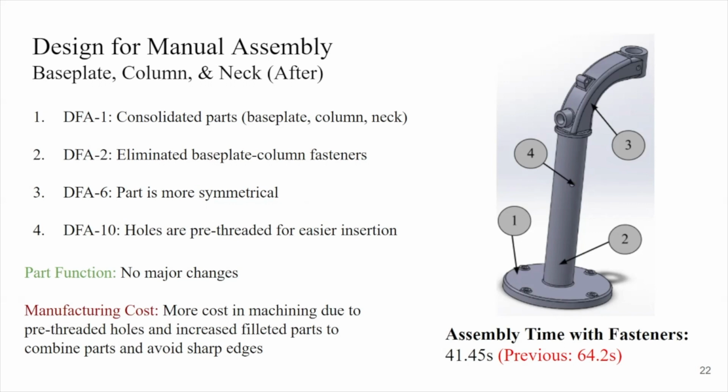For this part, there are no major changes to the part function since it could still maintain control and isolate motion. As for the manufacturing cost, there are some effects since there was increased cost in manufacturing due to pre-threaded holes and more parts to fillet to avoid sharp edges. We were able to reduce the assembly time from 64.2 seconds to 41.45 seconds.